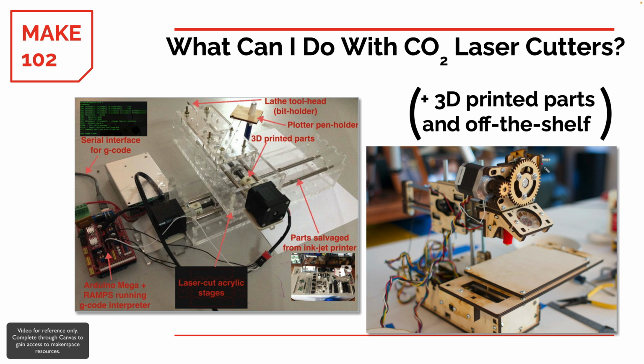For example, as well, consider the prototype on the right here. This is a 3D printer that is made primarily from laser cut wood parts. Now, we might never do this for a production product or even a final product, but we might decide to laser cut all of our components that can be laser cut initially out of a cheap material like wood to test everything before we build it out of a more permanent or more expensive material. This is a very good step in prototyping to do things quickly and cheaply to make sure that everything is going the way we want it to.